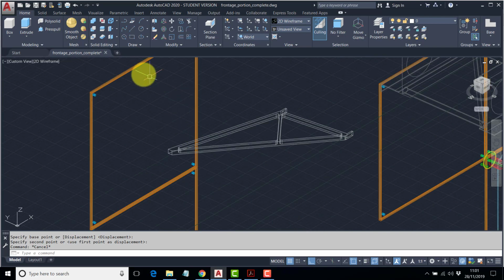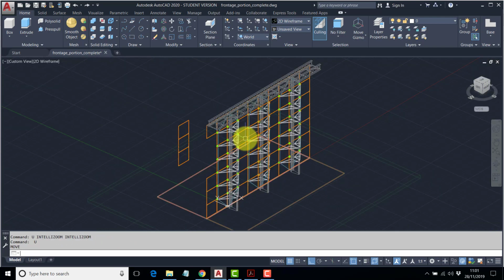We couldn't have these showing as hidden line and these not. You can't mix them up if you're just printing from one viewport. So what I'm going to show is how you set it up with multiple viewports, and you can then control the method of printing, what's called the shade plot setting, for each viewport.